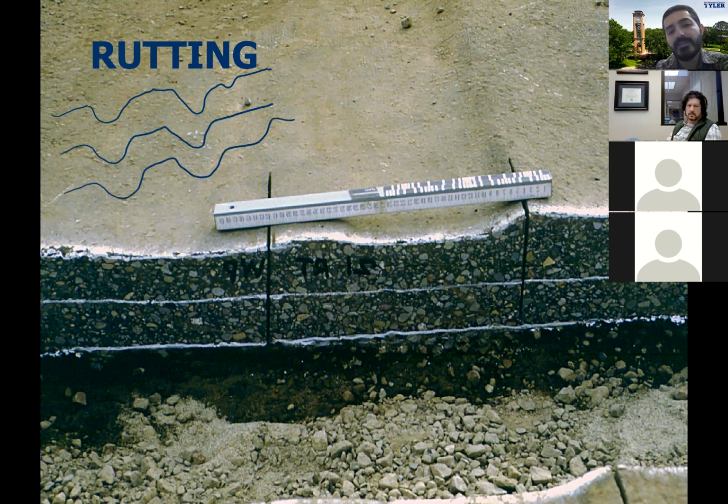So in this picture here, this means that the rutting is reflected across the board, not just the hot mix asphalt, but the base and the sub base. You see the depression across the board. And this problem means that there's a problem with the subgrade. The subgrade is too weak, or there are drainage problems. With the effect of traffic loading, it's going to lead us to the subgrade being the problematic part, because the whole structure is rutted.